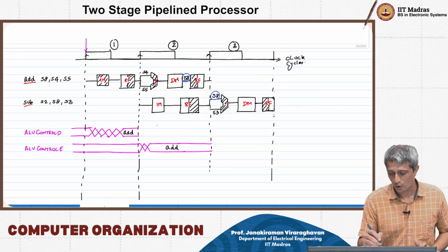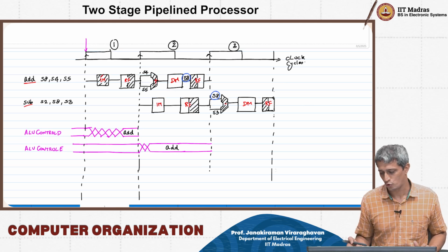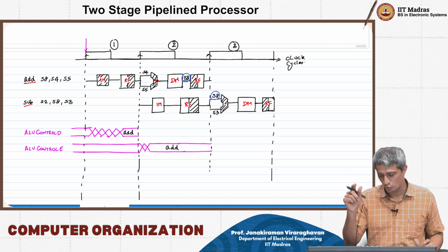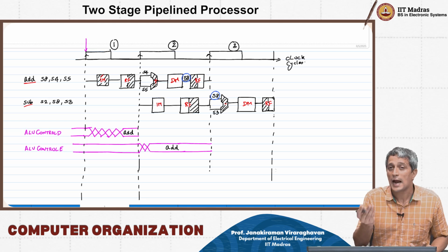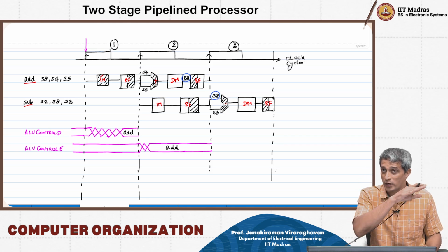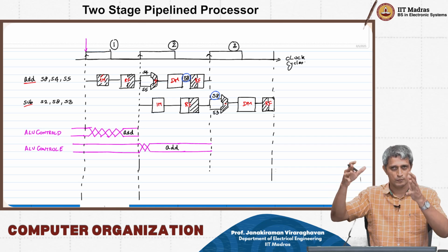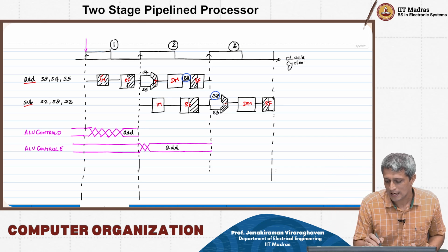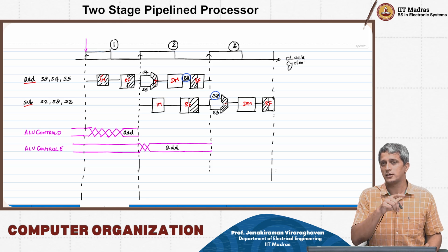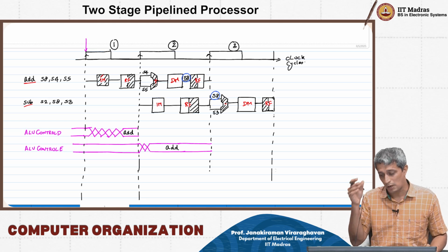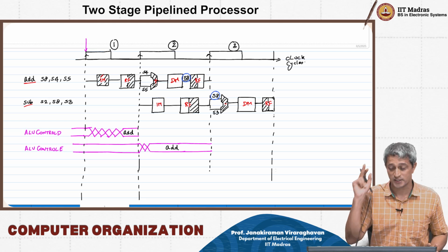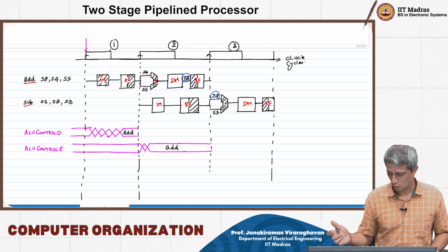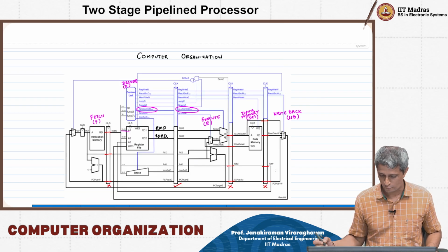So therefore, S4 and S5 are the signals that are coming out to the ALU. Contents of S4 and S5 have come out to the ALU through the RD1E, RD2E, and the ALU control has also got registered to add. The add operation can be performed in the ALU. It will take TALU for it to perform that operation, right? And then it is going to come out. It is going to bypass the data memory, come through that MUX, and this data needs to get written back into my register file. So that is a very important part, and let's look at how the signal is going to flow even for that.